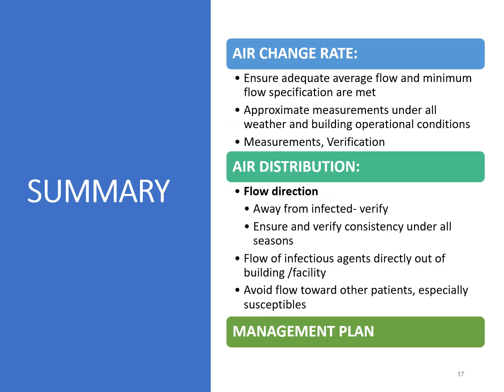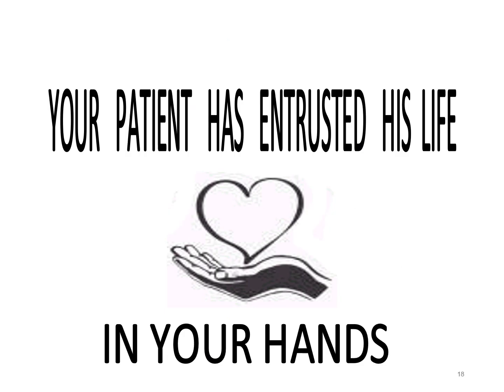To summarize, air change rate should ensure adequate airflow, and minimum flow specifications should be made. Approximate measurement under all weather and building operation conditions should be made. Air distribution should be from clean to dirty. Flow of infectious agent directly out of the building should be ensured. Avoid flow towards the patients and have a proper management plan. Your patient has his life in your hands. Thank you.